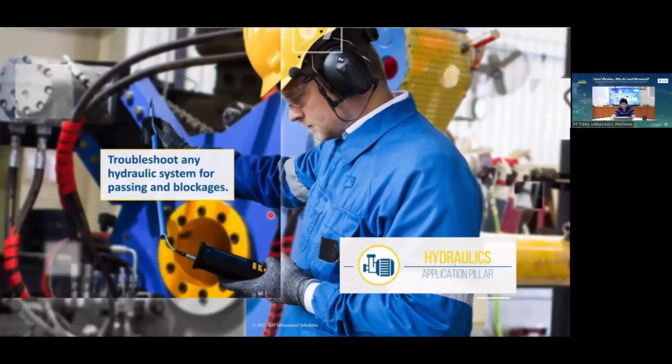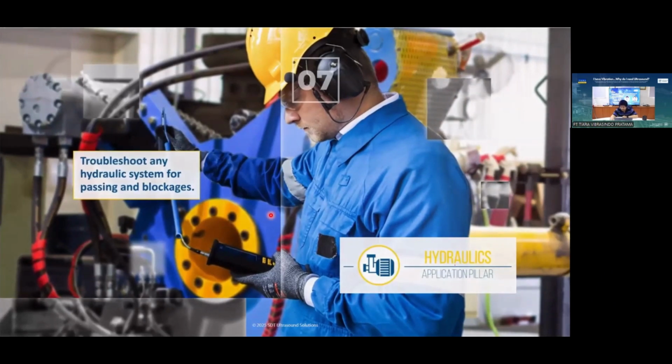And also, next is the hydraulic system. We can troubleshoot any hydraulic system for passing or blockage. For example, if you have four cylinders, you can compare from the first until the fourth cylinder. And how about the sound? For example, if you measure the first cylinder at 15 decibel, the second 16 decibel, the third 17 decibel, but the fourth cylinder is 2 decibel, that means it has an internal leak or something abnormal inside. So you can compare between the cylinders, measure the sound, and analyze which hydraulic cylinder has a problem.